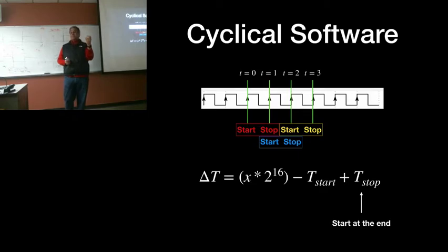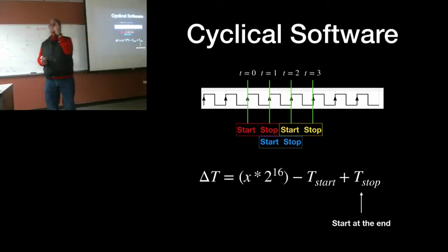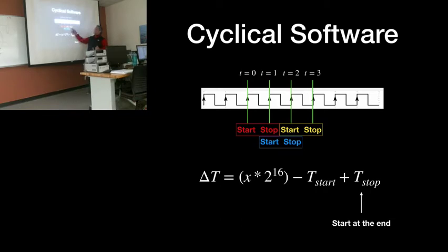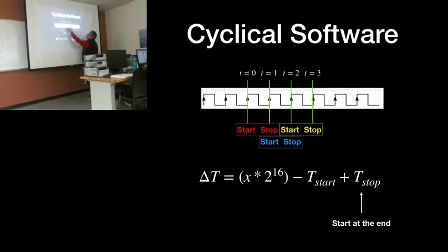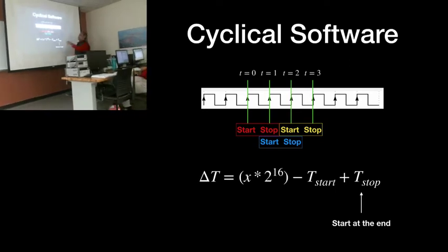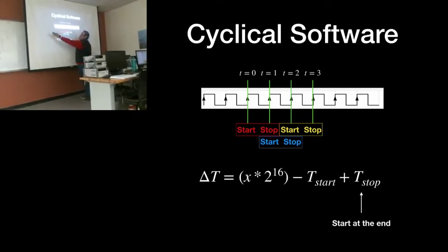And your code is going to be very complex. You have to make the assumption that you are going to begin from the end, so that when you see me coding now, I'm going to make the assumption that when I capture, I'm capturing the stop. Here's why. If I capture the stop, I'm making the assumption that in the past, I also captured the start. So when the stop shows up, I am ready to make my calculation. The problem is this: the first time your software goes through is going to give you junk data, because there was no start to the first event. So when this first event shows up for the first time ever, there is no start. I'm going to assume that it's a stop, make my calculation and then move to my next event. When that happens, that stop will now have a proper start, and I will be able to do my code.